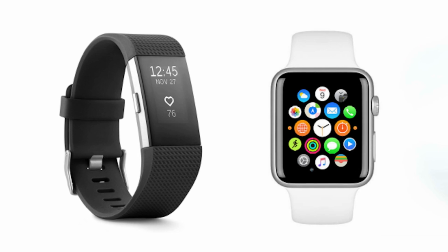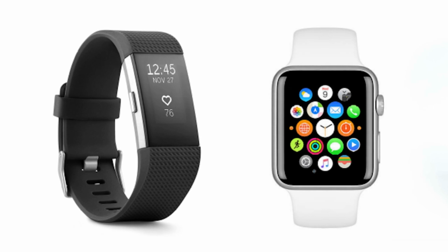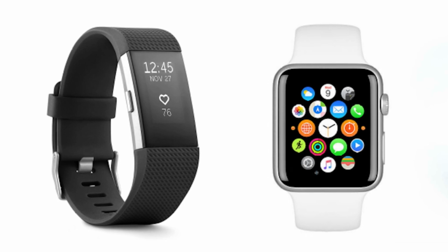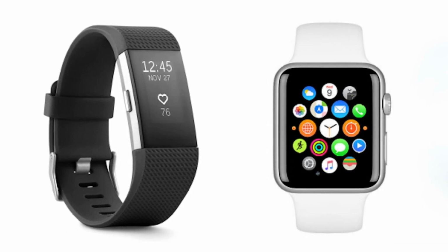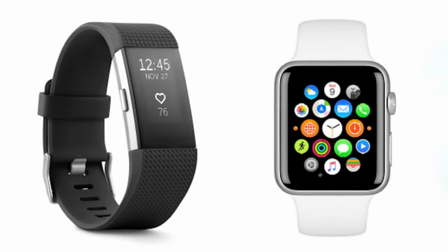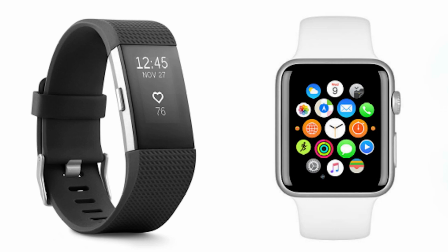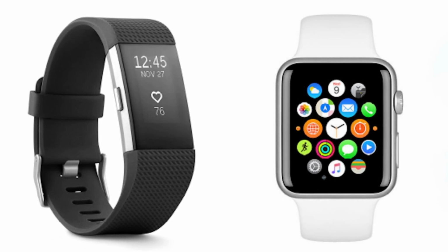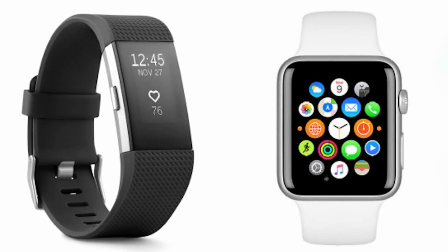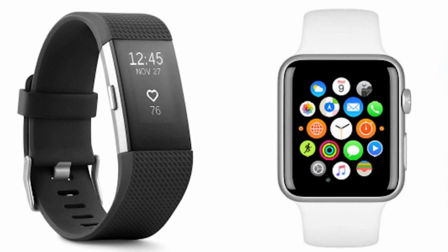Smart watches like Apple Watch or Fitbit watches are also a computer in themselves that make use of Bluetooth technology along with photoplethysmography, that is PPG technology, to record heart rate from the surface of the skin, that is the wrist. This method eliminates the need for a chest strap. The PPG shines light on the skin. The optical sensor measures the reflection of the light. The heart rate is determined by measuring how much blood passes through the illuminated spot as the heart beats.